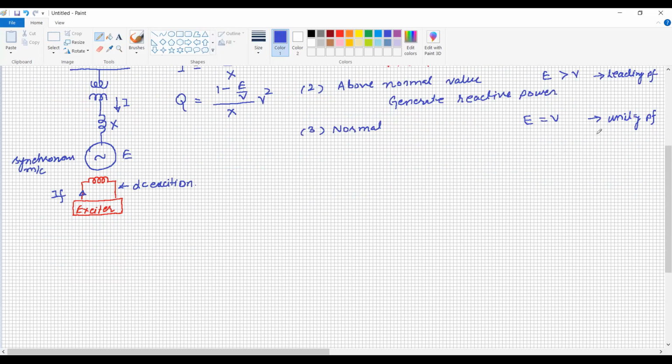system. So this can be explained with the help of the V curve and inverted V curve, or it may be the variation of excitation, that is, the variation of armature current with respect to the field current, keeping the load constant. The load is either a no load condition for generating. Say this is your armature current, and the power factor of the motor, and here is the field current, the DC field current, which is the excitation.